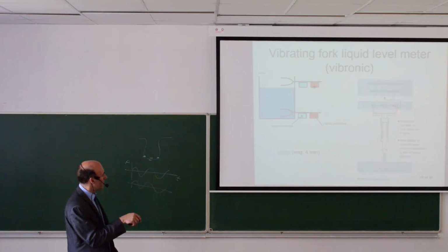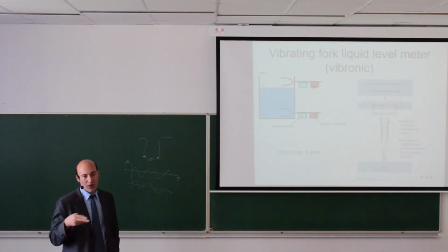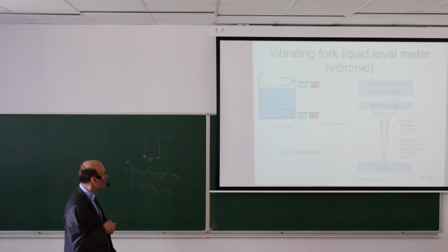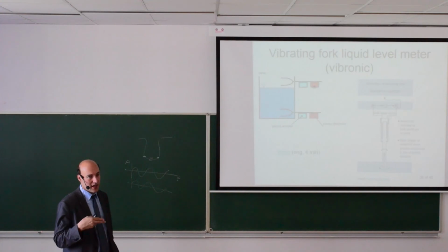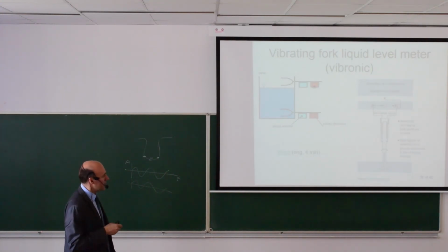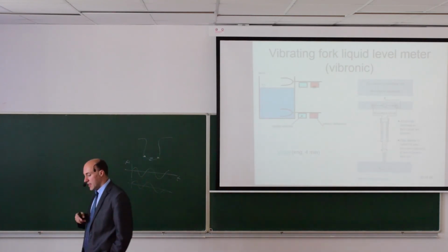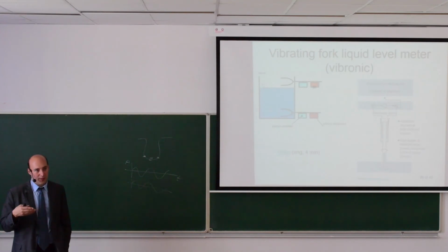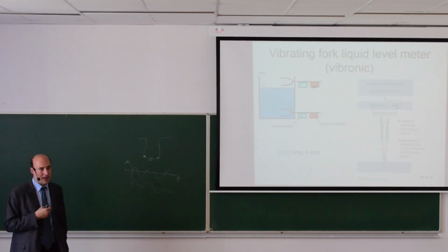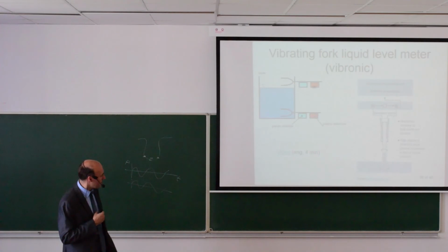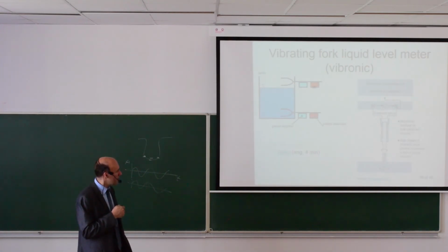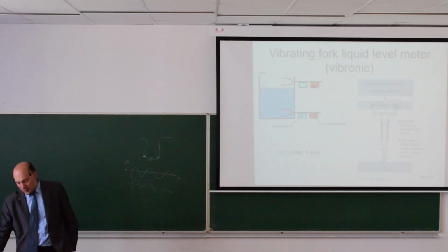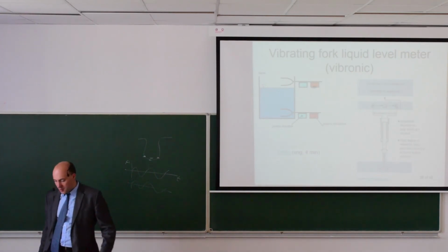Here you have a resonance circuit, a mechanical resonance circuit, so you make it move, and this tip is submerged in the liquid or in the solid, and we are looking for the change in resonance frequency, or the vibrations will stop completely if it's a solid material, for example. Now let's take a look at the video where we'll see how this works in an animation.